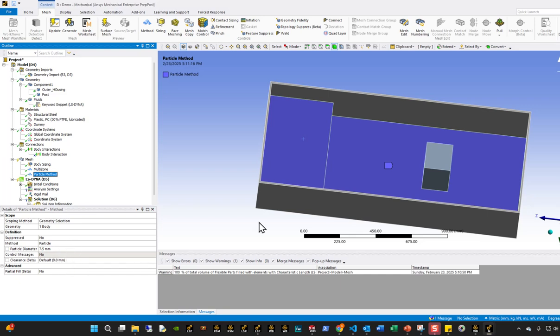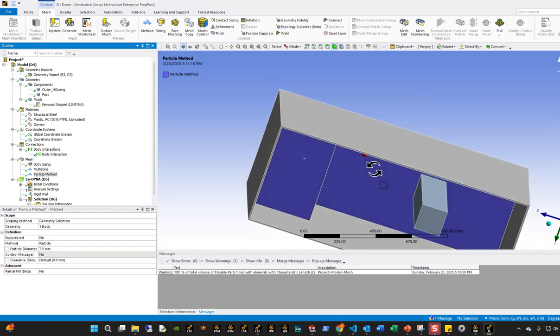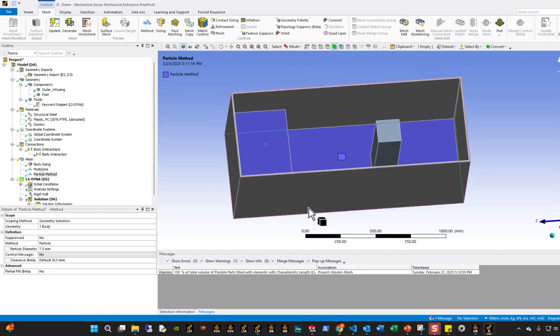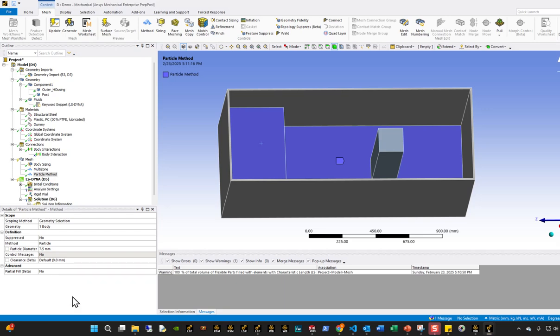Essentially, when we do a problem like this, what we really want is mesh independent results, by gradually decreasing this number and looking at the results. There are a few other parameters within the control SPH and the section SPH card that we'll want to adjust to make sure we get a good result. But it is very sensitive to the particle diameter, so we want to pay attention to this. It's essentially based on the kernel function that we're going to talk about in a second.